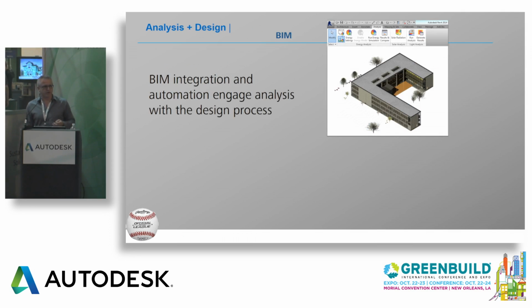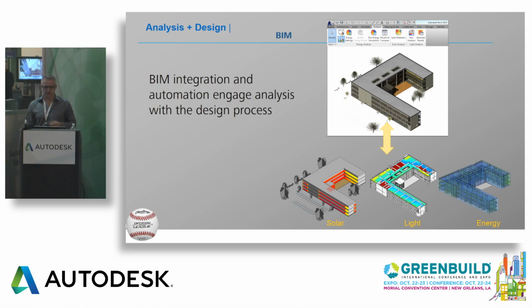Another value of having the analysis and the results integrated into the BIM process is that we can also have other tools like solar analysis, which we just released in labs yesterday, lighting analysis, and then energy analysis, which Ian just talked about. All these things operate on the same architect's model and keep up with the revisions done in the Revit model. So if you need an answer about how your shading device affects your daylighting and your solar radiation on your glazing, you can answer those questions with the same model.